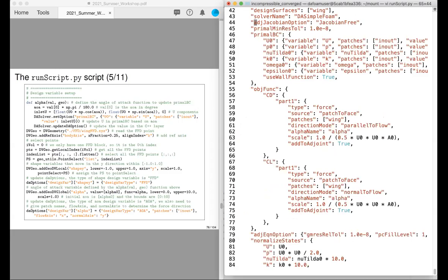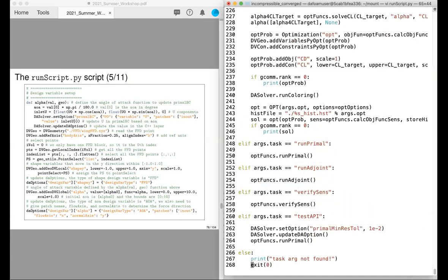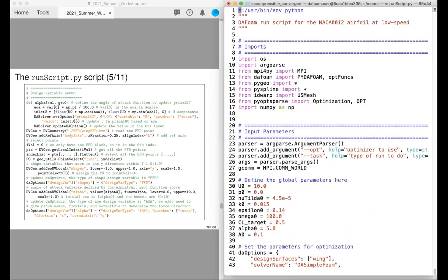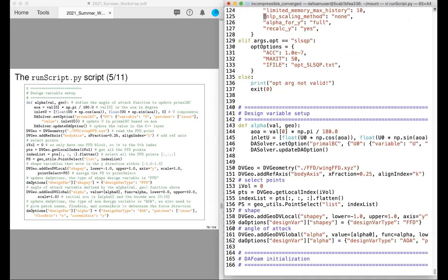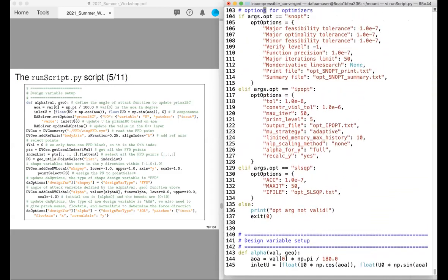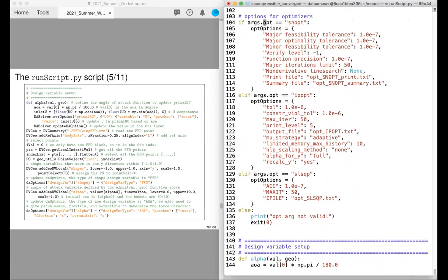It will automatically stop. The reason you saw that behavior is that the default option used the finite difference method to compute the Jacobians, which is not very accurate, which means that the adjoint gradient is not very accurate, like 0.1% accurate. Then a lot of times very near the end, you cannot find the correct gradients, so you cannot improve the objective function.